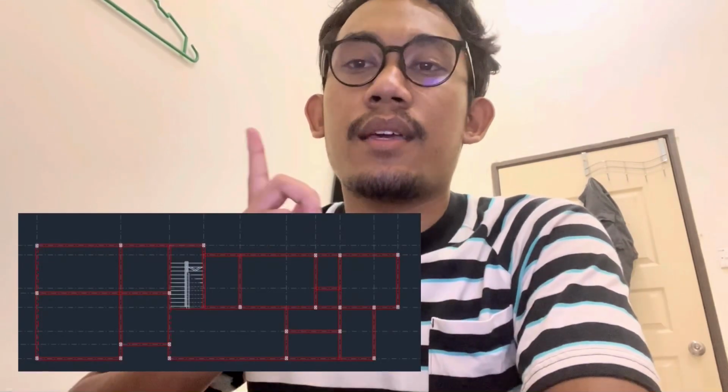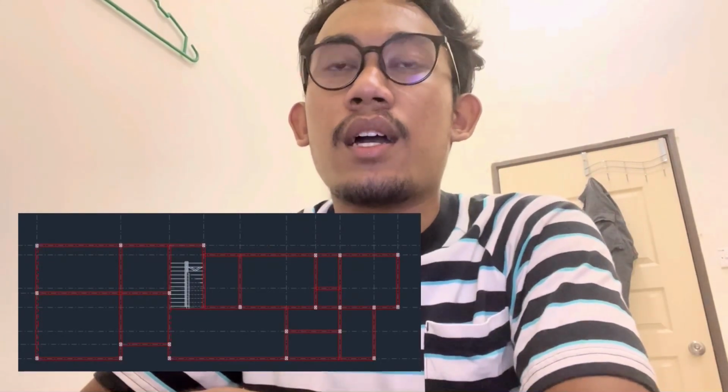Okay, I will present my beam that I calculate. Okay, this is my beam that I calculate, which is J1A3. The slab thickness is 150 millimeter. My unit weight of concrete is 25 kilonewton per meter cubic. My brick wall height is 3 meter, and then my weight of brick wall is 7.8.